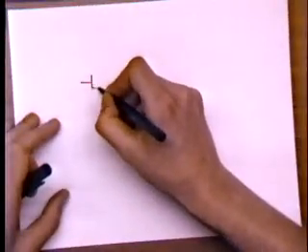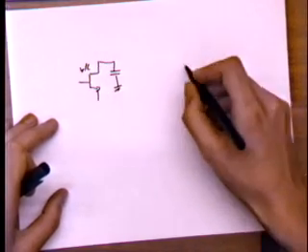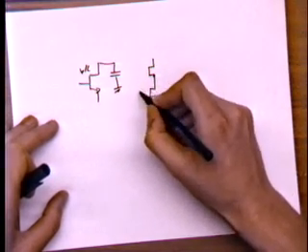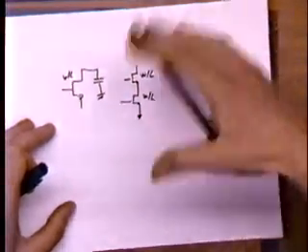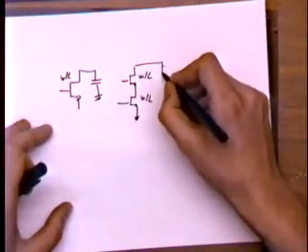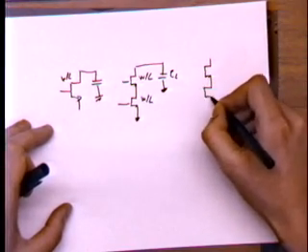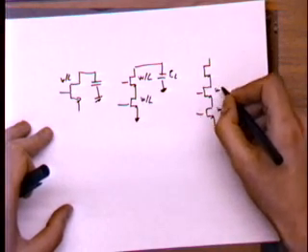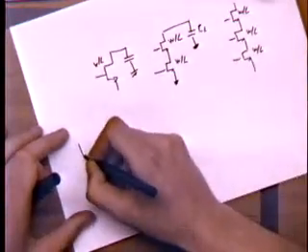So we start from a gate that is an inverter. I'm going to draw the pull down, but you can imagine the pull up, right? This is W over L. Then I'm going to make a 2 NAND, so 2 devices stacked. Each of these is still W over L. I'm not trying to keep the delay constant. I'm just trying to stack more devices. And I'm fixing also the load capacitance, so the load capacitance is constant. Then I try to do 3 devices. Then I try to do 4 devices.